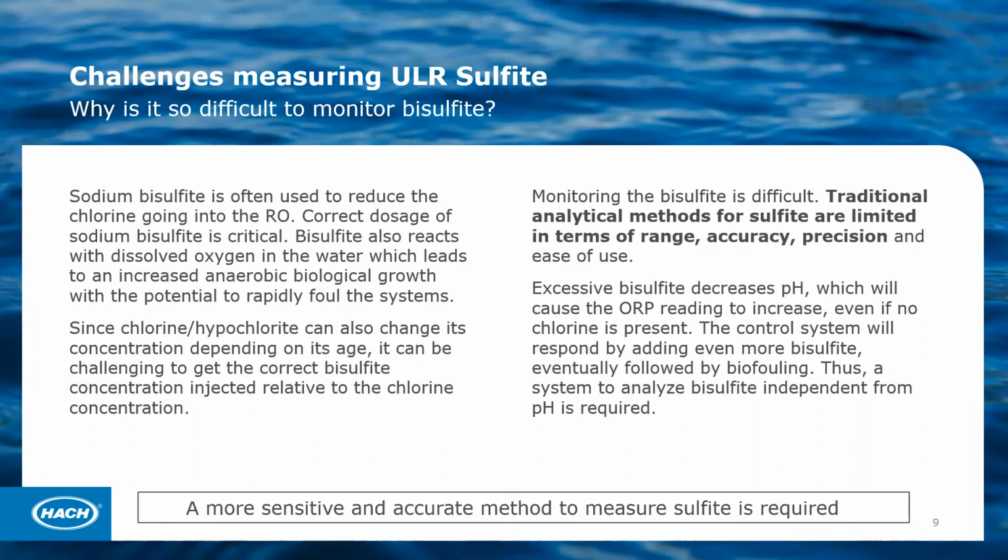We have our granular activated carbon in some sort of tank or system, and we push our feed water through that, and that charcoal grabs that chlorine right from the feed water, removes it through those physical means. And it's a great way to not have to pay for additional chemicals. It's a great way to make sure that we don't have additional chemicals after dechlorination to deal with downstream.